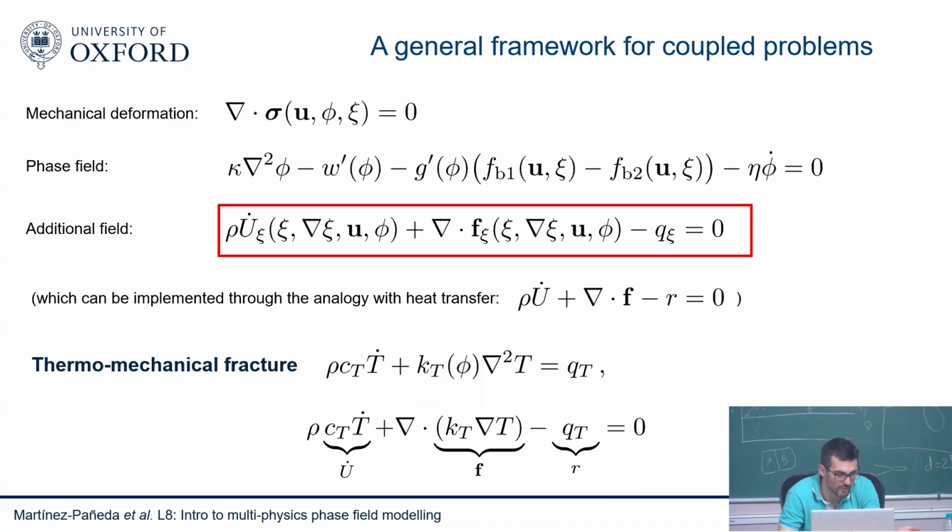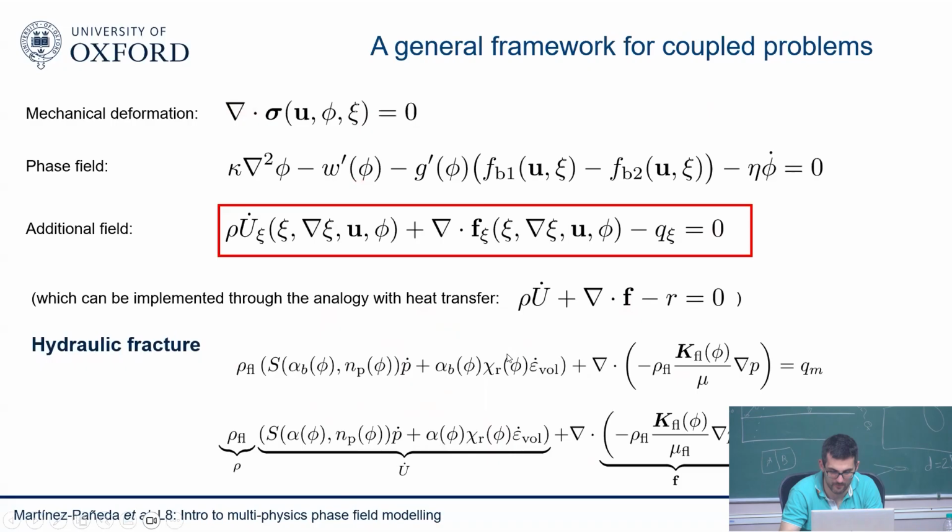So the easiest one is thermomechanical fracture. You will solve a mechanical problem, a phase field problem, and this additional field will be temperature, and you can see how you accommodate each of the phenomena. If you're dealing with hydraulic fracture, remember we need to solve a mechanical deformation problem with an effective stress per mechanics, a phase field fracture problem, and then your additional field will be pressure, where you use Darcy's law. So this is the equation that we solve in hydraulic fracture, Darcy's law.